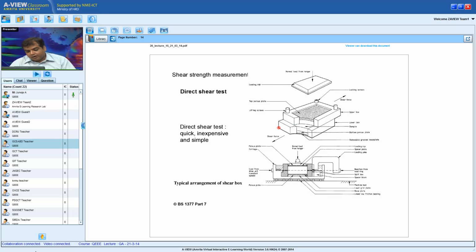So a normal stress in this direction is my minor principal stress. Likewise, I can have another plane in the third direction, which is again perpendicular, and this would be my intermediate principal stress. So minor and intermediate, before the start of the test, have the same magnitude, right?